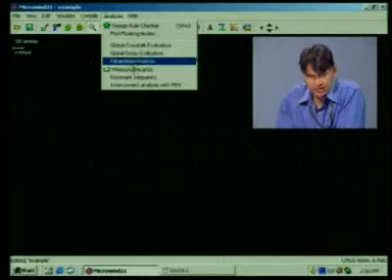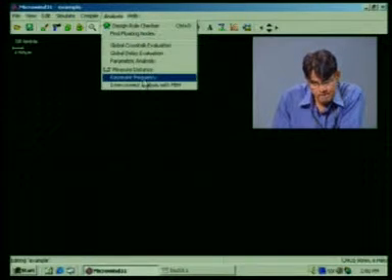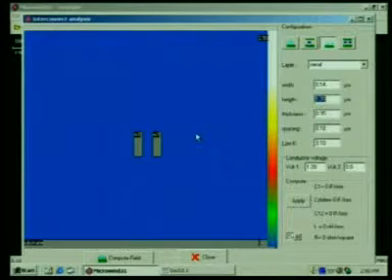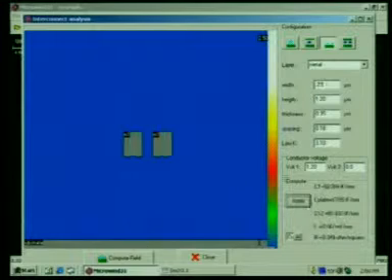There is a lot of analysis. I will explain this one, the interconnect analysis. Suppose I have these two buses in my design. You can imagine the PCB, there are two interconnects. I have maintained this width, this is the default, you can edit that one, apply, and after that you can edit height, thickness, everything according to your requirement, and then you can select the copper or aluminum.